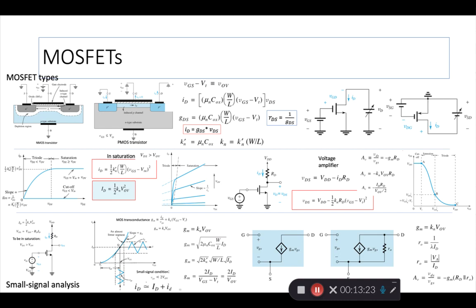There is that collector current that is the product of IS, which is a constant, times e to the power voltage, right? So similar thing here. The voltage is the input, the current is the output. Here we have a square relationship, and everything else is constant. So ID equals something times V squared gives you the current in this drain circuit, and this voltage is actually the voltage on the input side, right?